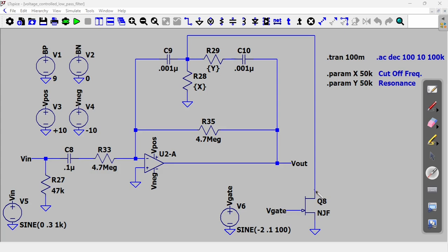So V gate, as you know, and here the source is grounded. And this is a true ground, as opposed to what's in the schematics of the book. As you know, VGS, or VG in my case, is supposed to be negative. It cannot be positive in theory. And the higher V gate is, so the closer to 0, the smaller the resistance in this path.